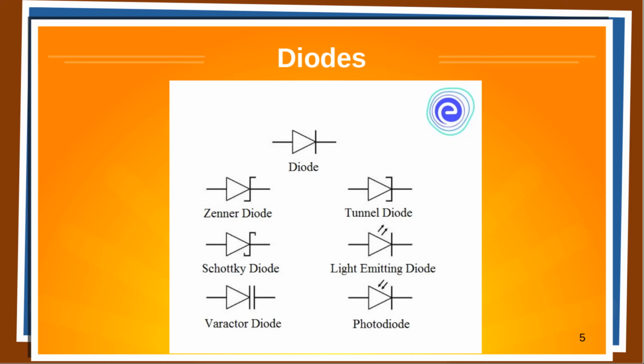When the electron at a high energy, when it's free, goes into a hole, it gives off that energy. That energy is in the form of photons and phonons. You've probably heard of photons, that makes light, whether it's visible or not. Phonons are lower frequency energy, which causes vibrations or heat. So that's where the heat dissipation comes from.